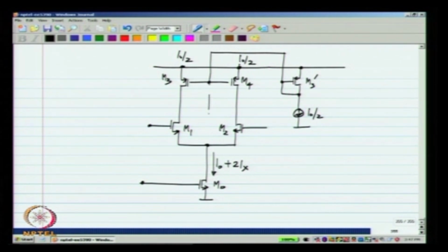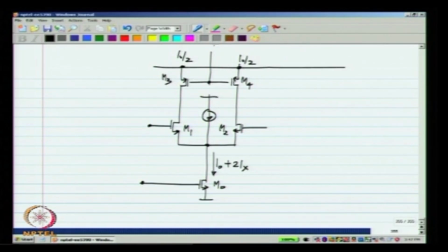Now, how can I make a current source that provides current, that pumps out current? The easiest way to do that is by using a PMOS transistor. Okay. Let me remove all of this, I will label this Vg3. Okay. Now, a current source like this, which can source current, can be implemented using a PMOS transistor, okay, with the gate biased to some voltage.